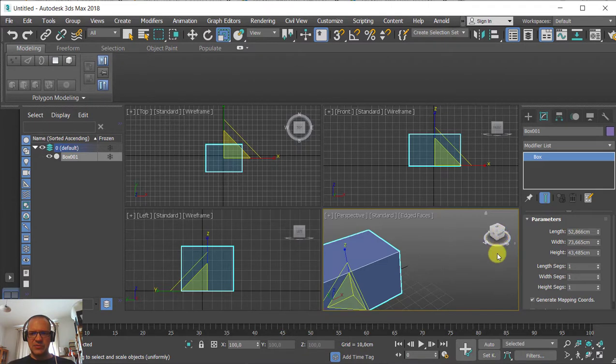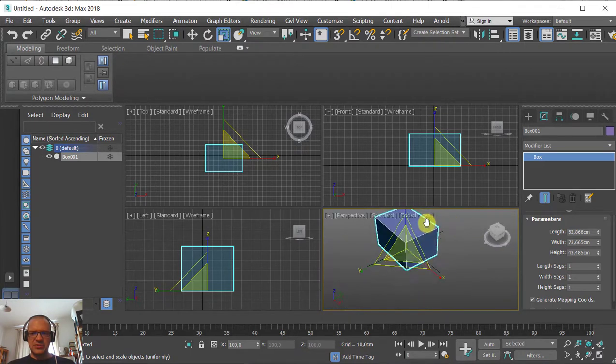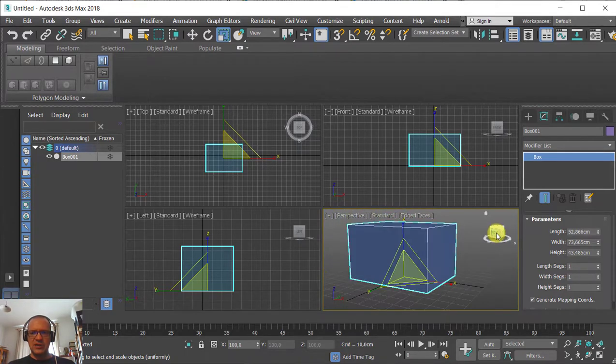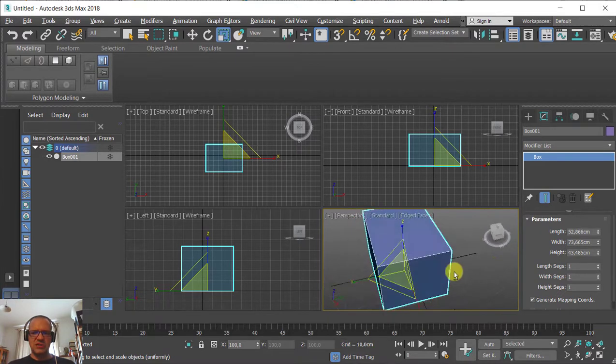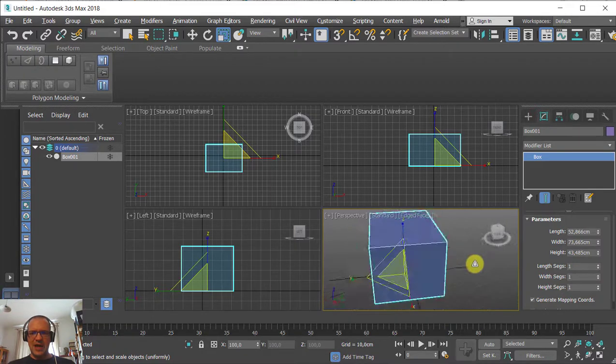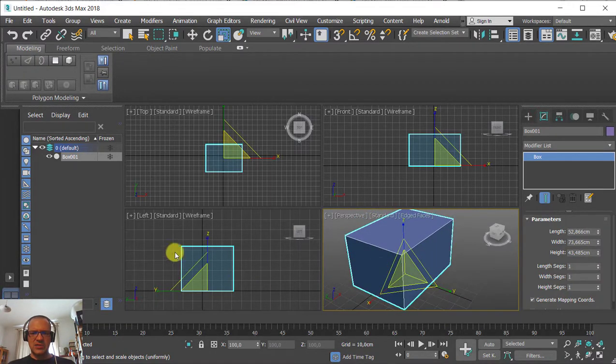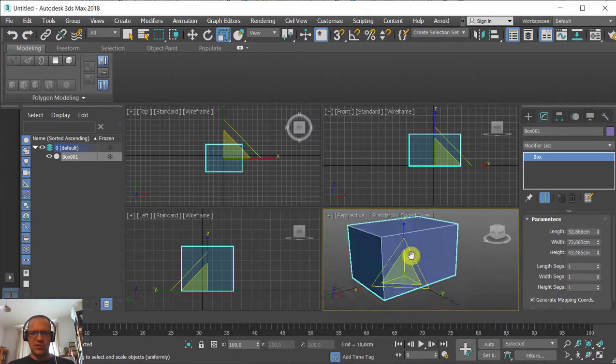If it tells you the front, it helps you understand this is the front direction, okay? So even if you are not using this viewport key because you're using the hotkeys, it can give you information about which direction is which. So this is front, this should be back, this is the right side, this is the left side. So in the left view, you will see this side of the cube.